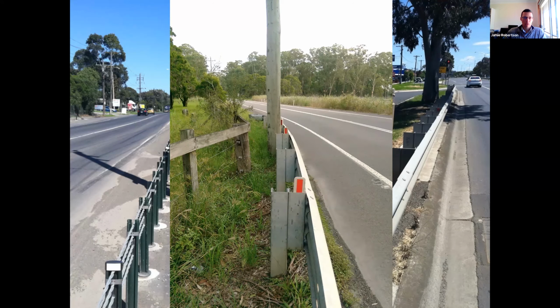So I guess don't get too hung up on not achieving every desirable parameter when it comes to barrier design. Take all the steps that you can to minimize deflection, choose the product that best suits the site and so on. Document any non-conformances, but don't be deterred from putting a barrier in if you think it is going to provide some benefit still.